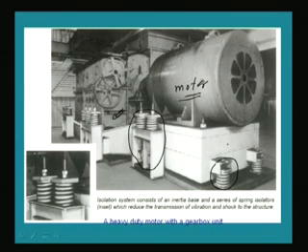You can see here the close view of the oscillatory system. Generally, we provide this oscillatory system so that vibration does not go from the machine to other foundations, because it may disturb the nearby machines. Also, if a lot of vibration is there in the machine itself, then we will have failure of some of the components due to fatigue, because it gives cyclic stresses to the members.